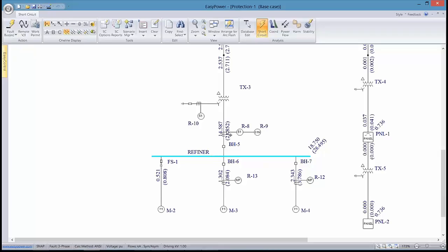And so the worst case, there could be as much as a 5,000 amp pulse differential because of that DC effect. If we look at what's going on at the 5-cycle point, you can see the offset is much less, because by this time any DC effect will have essentially bled. If we look at 30-cycle, it's pretty much gone.